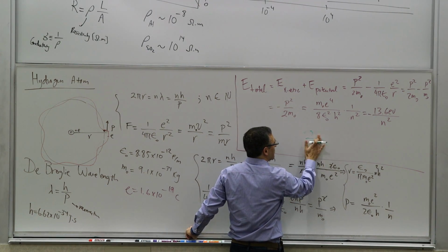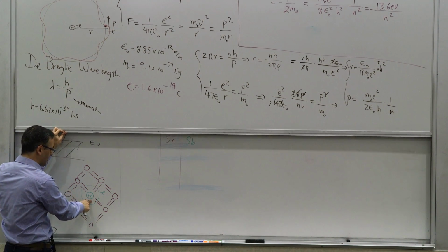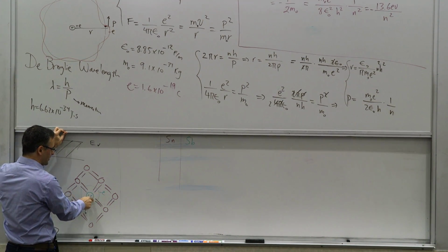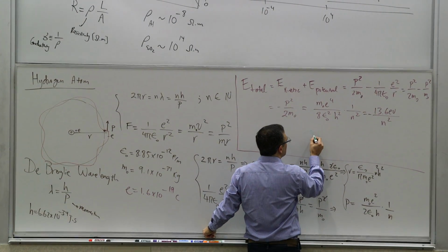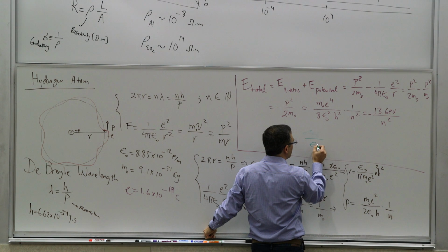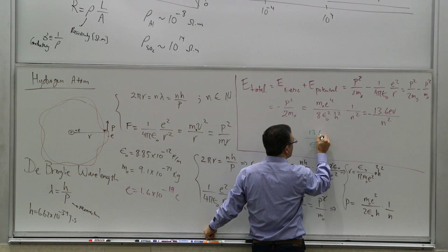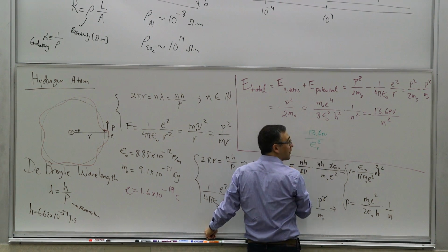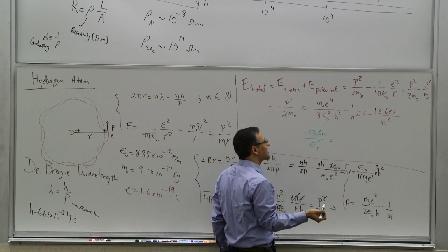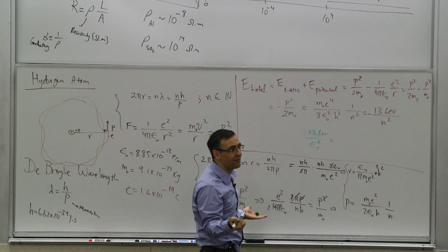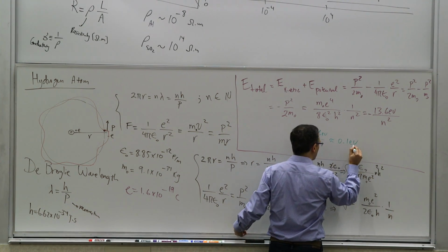scaled. So this energy level, let's say the hydrogen. So this kind of looks like a hydrogen if you think about it, because it's one positive electronic charge and one negative electronic charge, except for the fact that it's inside silicon. So now this is going to get scaled by epsilon r squared. So your 13.6 eV is going to get scaled by that. So the largest energy level that you will have would be 13.6 divided by 11.7 squared, which is roughly 0.1 electron volt.